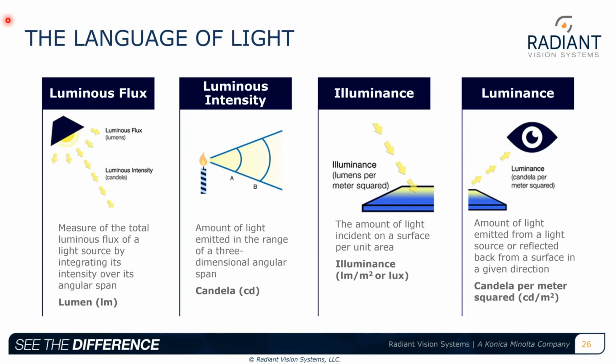That's the photometric unit. We have photometric, and then the larger category that photometric is a subset of is radiometric. That means basically not at all filtered by the human response. The radiometric equivalent of lumens is watts. So if you go to the hardware store to find that light bulb, sometimes it might have lumens. It might also tell you the watts. So this is the luminous flux.